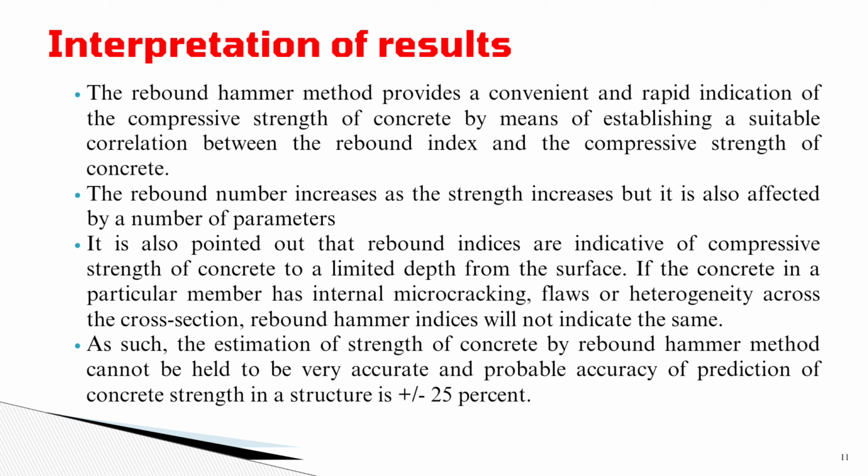As such, the estimation of the strength of concrete by the rebound hammer method cannot be held to be very accurate, and probably the accuracy of prediction of concrete strength in a structure is plus minus 25%.